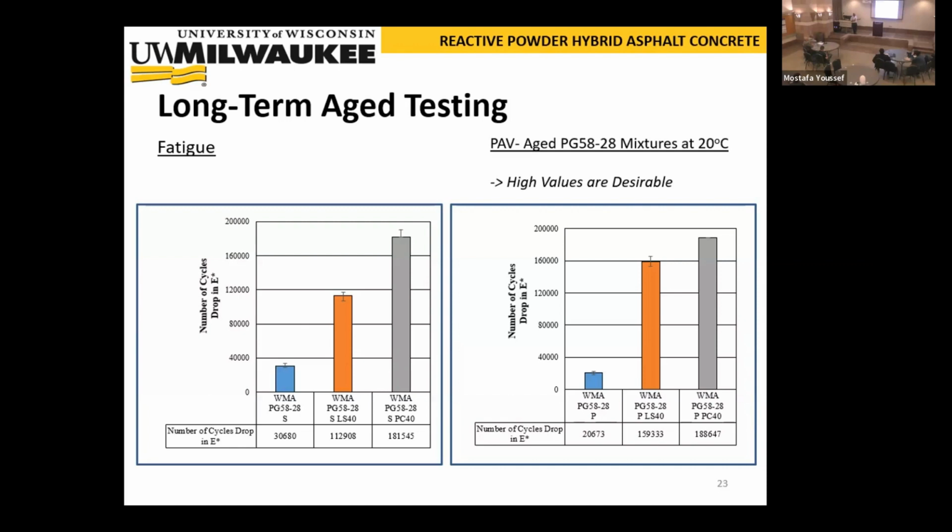So for warm mix binders with polymer modification, it seems that the dominant contributor to fatigue resistance, or crack resistance, in our case here, is the cement, not the polymer, unlike what we saw at the binder level. This could be explained in many different ways, maybe because of an increase in aggregate to binder adhesion, or increased cohesion in the binder phase because of the cement. We didn't really go that deep yet, at least in this study.